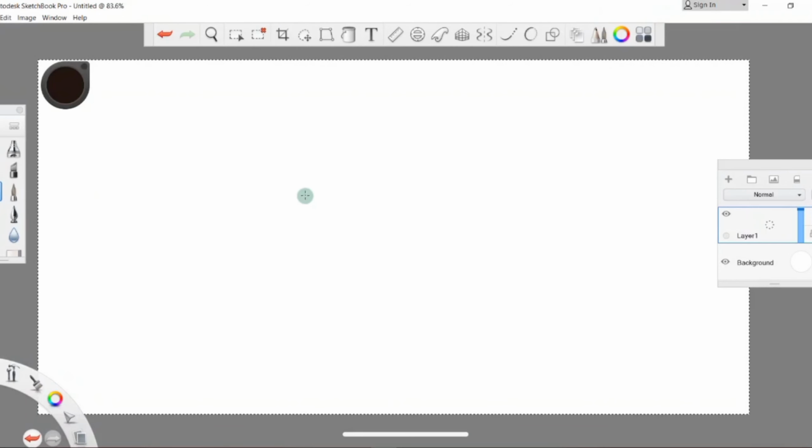We're gonna tell STAAD Pro, we'll tell that we know in this case our column is, right now the connection is like this, okay, this is the center of the column. The width of the column is 0.1 in our case. So we will tell the STAAD Pro to offset this face here,